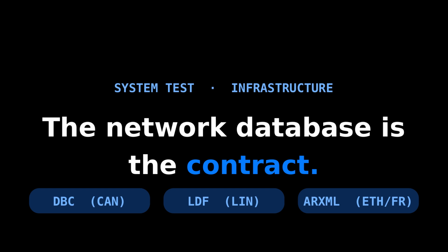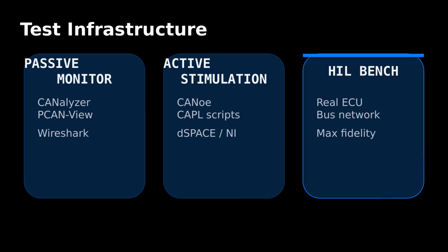Let's have a look at the different tools that you can use for that. For passive capturing, use CANalyzer, PCAN-View, or Wireshark. For active simulation, you have CANoe or CAPL scripts.